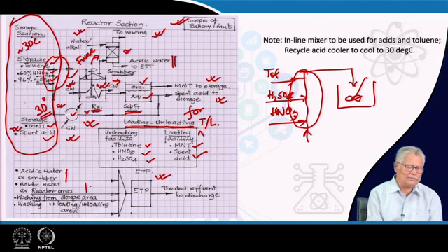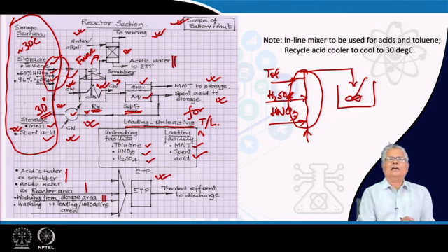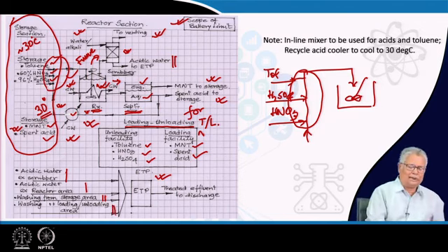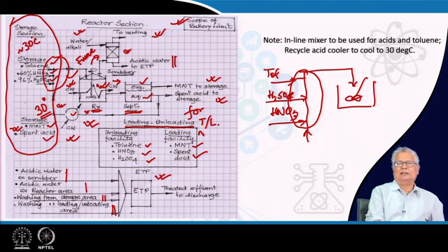So, you are going to receive some amount of acidic water from the reactor area, and you are also going to receive a good amount of wash water from the storage areas, and there will be wash water from your loading and unloading facility as well. It is expected that your wash water will contain a small amount of hydrocarbon, and it is also expected to be acidic. The acid has to be neutralized. That should be the first step before it is treated further and sent out as effluent discharge from your plant.